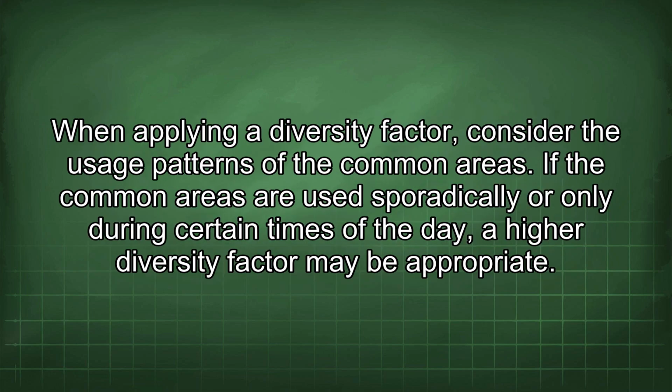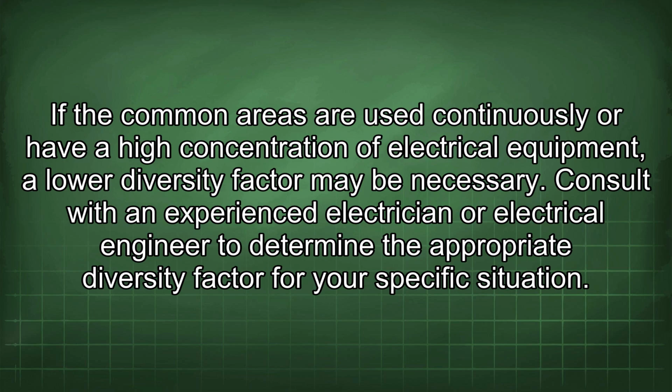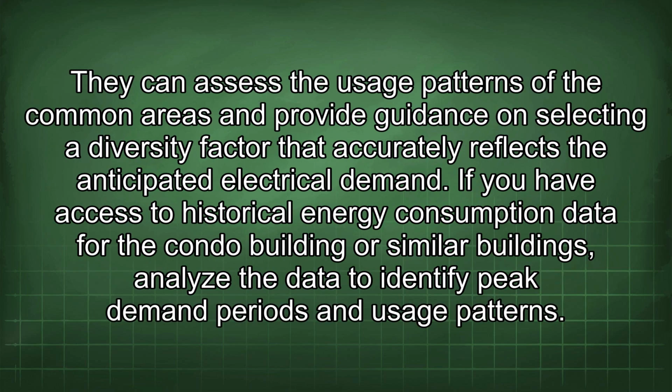When applying a diversity factor, consider the usage patterns of the common areas. If the common areas are used sporadically or only during certain times of the day, a high diversity factor may be appropriate. If the common areas are used continuously or have a high concentration of electrical equipment, a lower diversity factor may be necessary. Consult with an experienced electrician or electrical engineer to determine the appropriate diversity factor for your specific situation. They can assess the usage patterns of the common areas and provide guidance on selecting a diversity factor that accurately reflects the anticipated electrical demand.